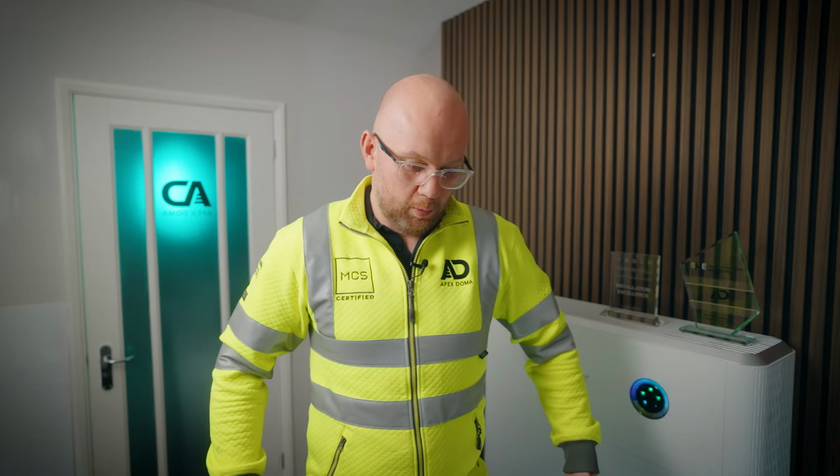And from a size point of view, these are about 700 mil wide. So normally I say, if I can stand with my back up against the wall, a battery storage system would normally stand where my body would be effectively. So if you allow that in terms of spacing, then that's normally a good starting point. So where can inverters go?